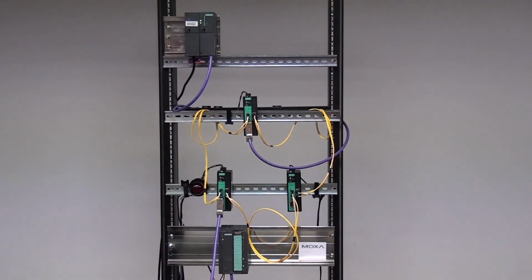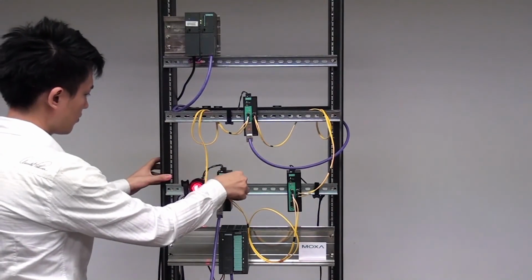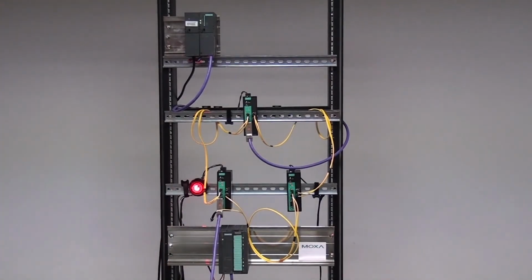However, the PLC is only able to detect an error when the Profibus traffic has stopped completely, which means that the PLC will be blind to any cable failures such as this one because communications are continuing down the backup line. Luckily, with fiber diagnosis, the ICF-1280I can step in.